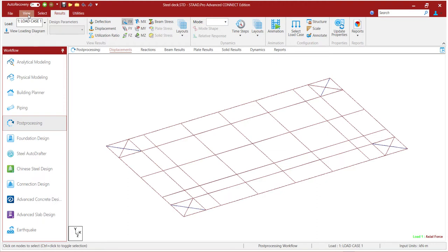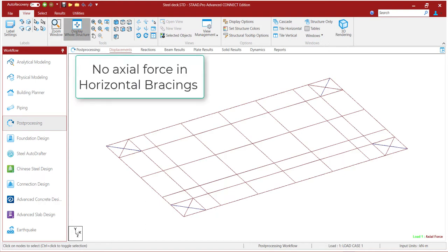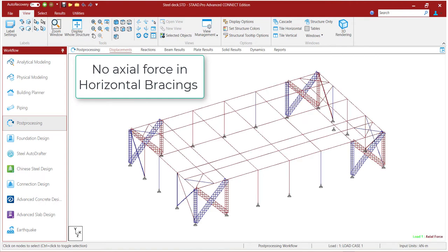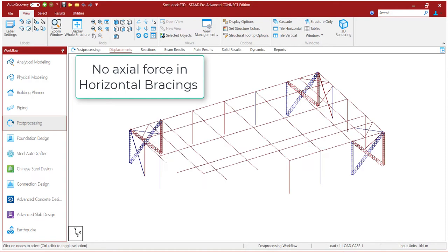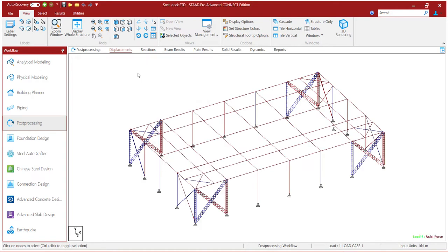That means all the lateral forces are taken by the diaphragm itself, because you have defined it as a rigid diaphragm. With a rigid diaphragm, you can't expect any kind of internal deformation. That's the reason any member connected with that rigid diaphragm in the same plane won't experience any axial deformation, and that's why they won't attract any forces. But that is not the real case in a real-life scenario.